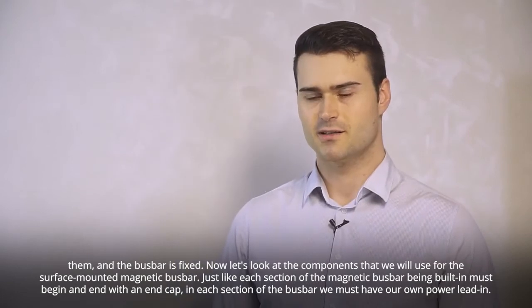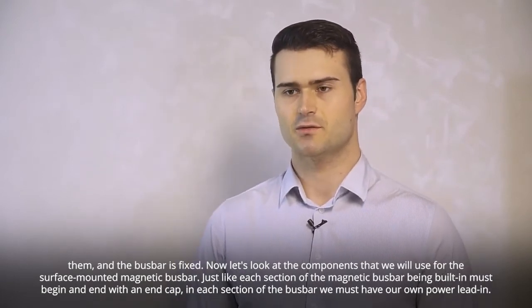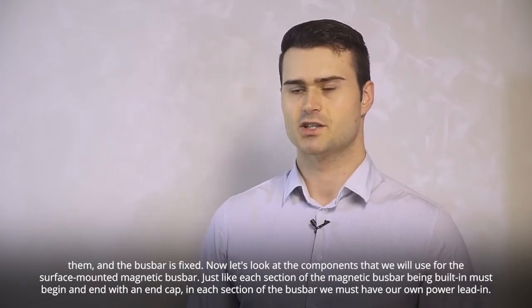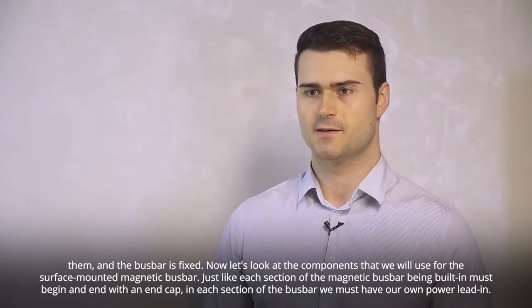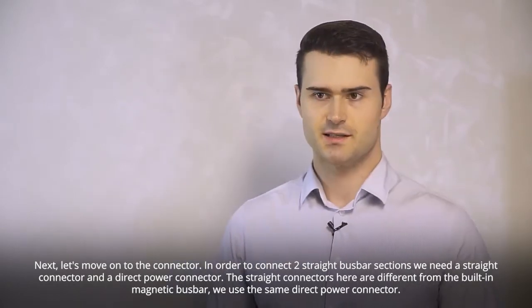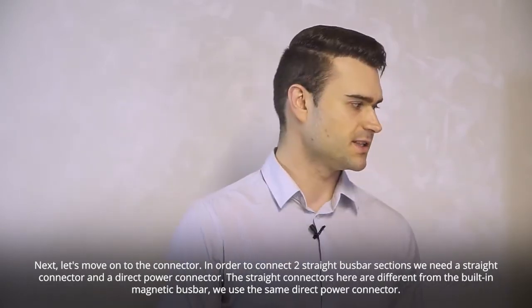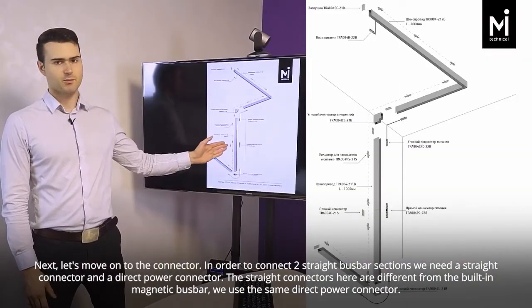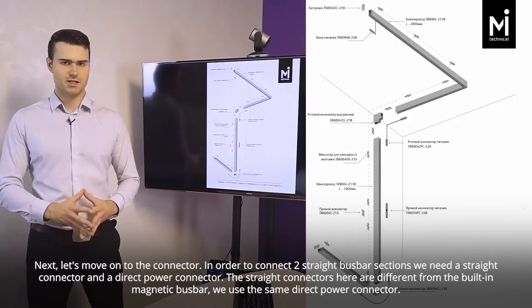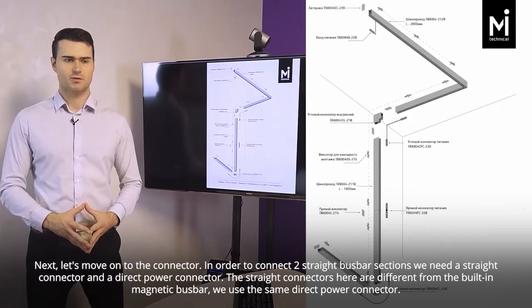Now let's look at the components that we will use for the surface-mounted magnetic busbar. Just like each section of the magnetic busbar being built in must begin and end with an end cap, in each section of the busbar we must have our own power lead-in. Next, let's move on to the connector. In order to connect two straight busbar sections we need a straight connector and a direct power connector. The straight connectors here are different from the built-in magnetic busbar. We use the same direct power connector.